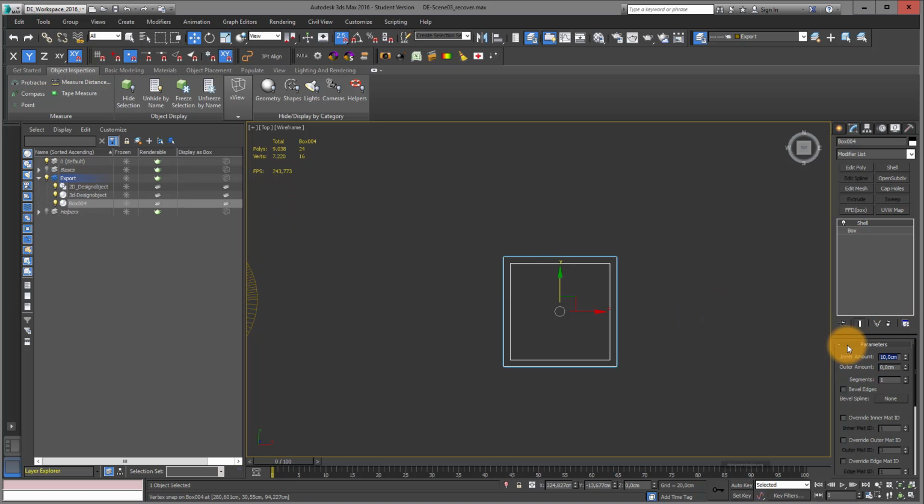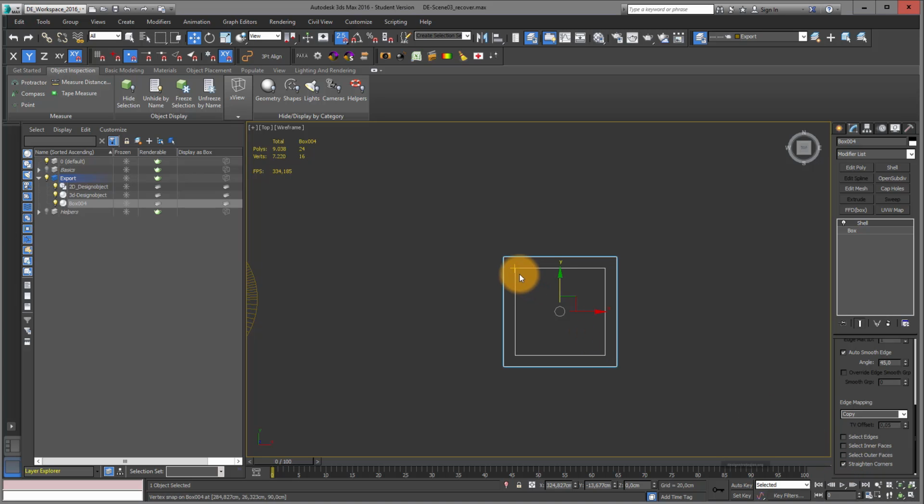And there's one thing also in terms of the shell modifier. It always tries to interpolate between these edges. So if you really want to have 10 centimeters, just keep in mind you always should have straightened corners on. This is not really done for designers and architects. It's more like face modeling and something similar. So if you have something orthogonal, always use shell modifier with straightened corners.